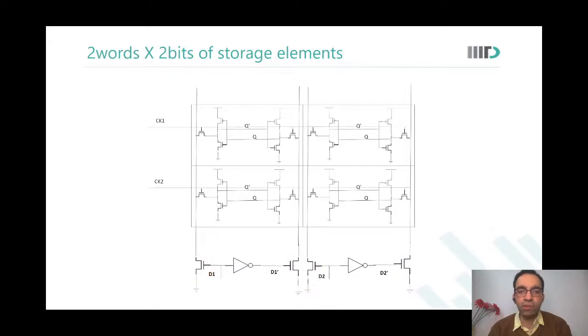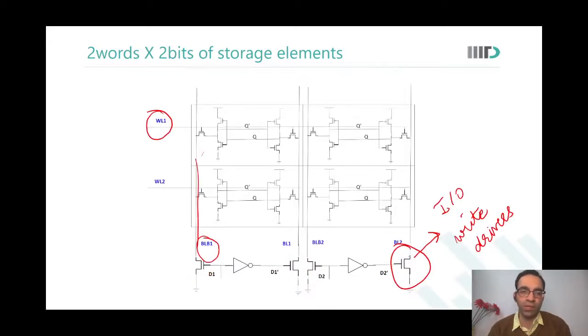Decoding means you select something based on the address information. But technically they are not different clocks, right? They're different word lines, but connecting to the same clock, depending upon the address bit. Yeah, so you gave the clock only to the selected word. Okay, so there's actually only one clock. It is only connected to different word lines depending upon that.